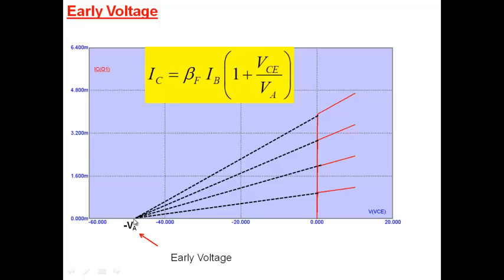So 50 volt here. Note that if IC is equal to beta times IB, the early voltage is 50 volt here, and I apply 2 volt here. So if I apply 2 volt here, 2 by 50 is a small quantity. If you're doing a quick analysis, it may not make too much difference to your collector current value. But we'll see at another place it is very important.